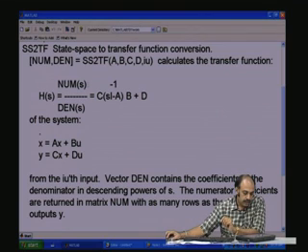And this will basically use this kind of an algorithm: C (sI minus A) inverse B plus D. In fact, this is what we derived in the last class, if you remember, of this particular state space form where A, B, C, D matrices are as defined for a general state equation. So, let us